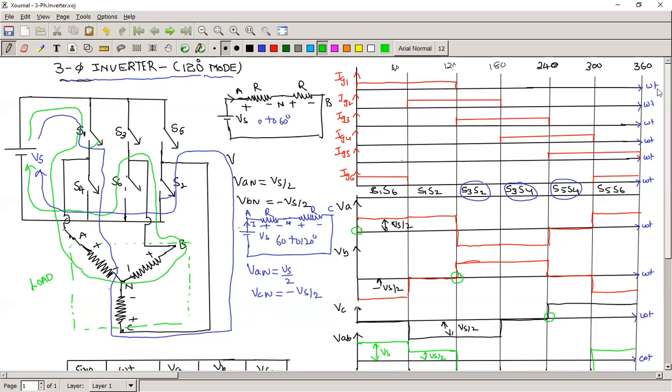One more important point is here. This is the switch. Generally in an inverter we use BJT, MOSFET, IGBT. We never go for the SCR because, with the input DC voltage, it requires a commutation circuit, so the circuit complexity and the cost of the circuit will increase.